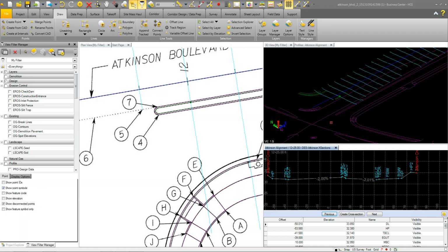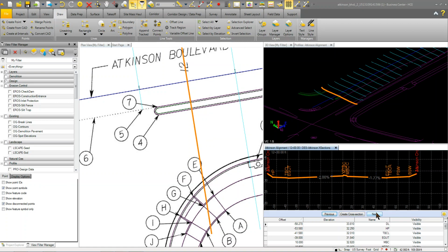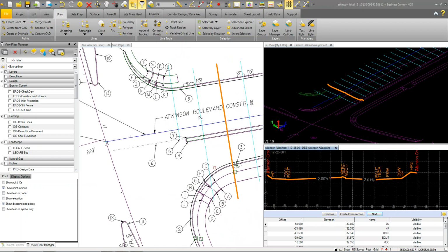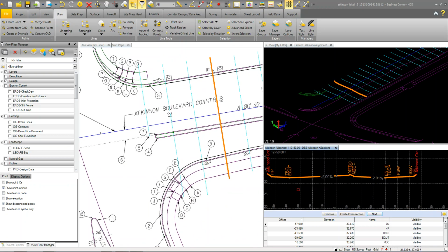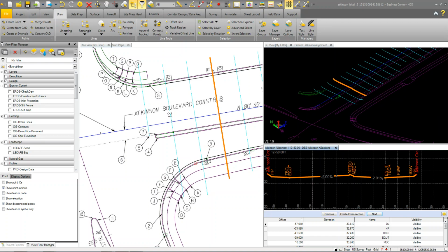And you can see that everything in purple has got no elevation. It's just my 2D line work that I'm working with. This view here is the cross-section view. So those are the stored cross-sections. You can see that I can jump from one to the other. And so I'm going to start at this one. What I'm going to do is elevate this curb line using this data and make sure that I tie through here and use the stakeout information and tie to the cross sections that were provided. So just to give you a little bit of background of what I'm doing here.